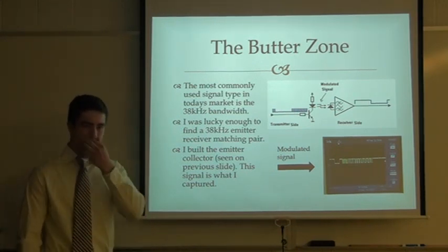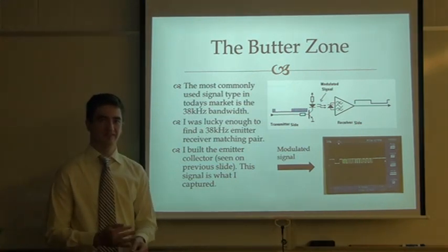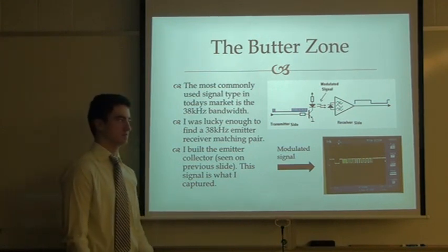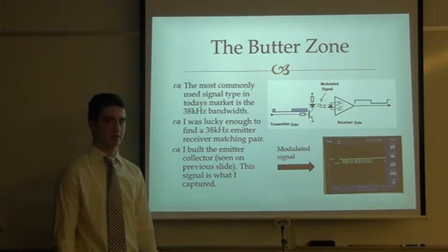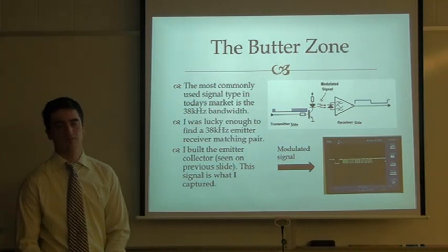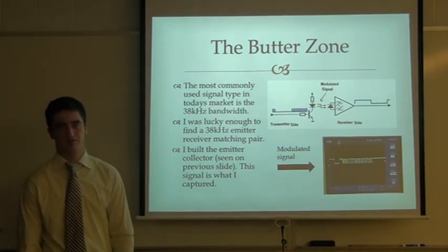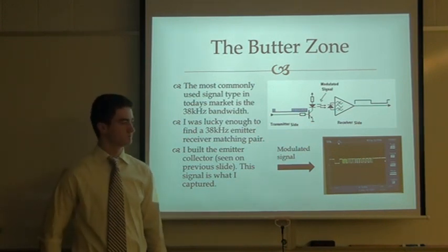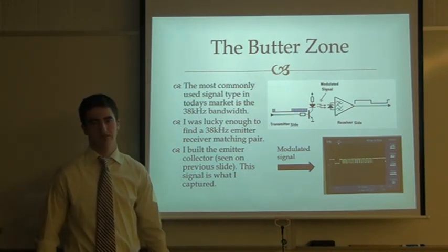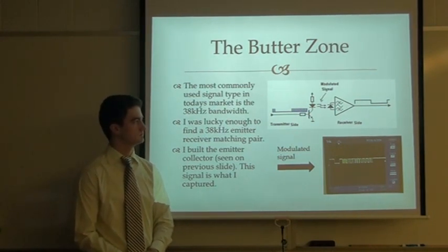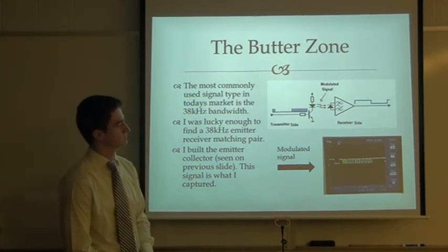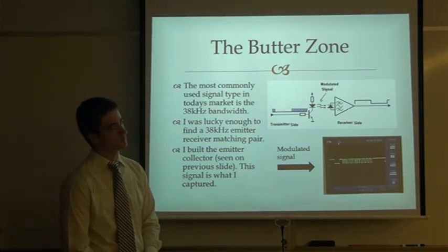So, if you do the math, 1 over 38 kilohertz is something like 27 microseconds. So this is actually a lot larger. This is huge, yeah. So what's really happening is there are hundreds and hundreds of the 38 kilohertz pulses wherever it's high there. Okay. And if you want to think of it as an envelope that encloses those peaks and sends a high signal, that envelope represents the high. Right. And your little 3-pin device is looking at the pulses you see in the top diagram, but converting it for you, essentially filtering it for you to produce the diagram at the bottom.